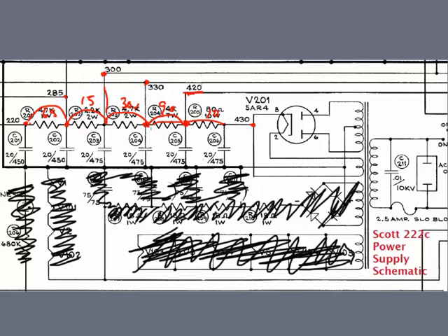So it's just plain old voltage divider rule going across these things. You could add up all these resistances to create the equivalent RT, add all those up, and you would find out what the total resistance is. You could then, from the total resistance, do I equals V over R, 430 divided by this total resistance would give you your current. You could then multiply that current times the resistance of each one of these to get your V. And in this case, it would have been 10 and 90 and 30 and 15 and 65, if all that makes sense to you.